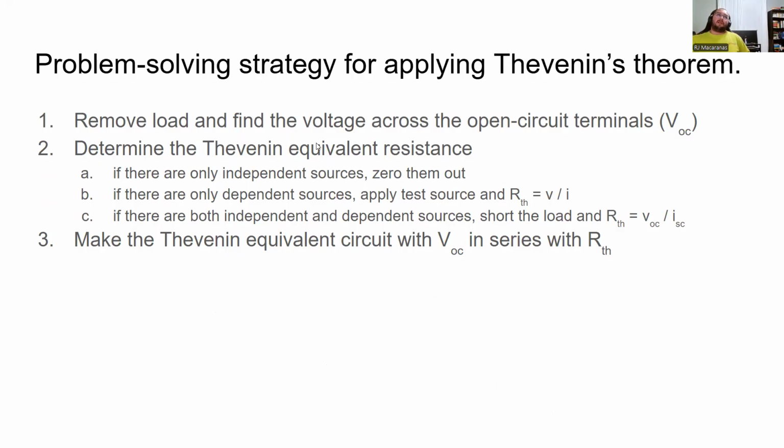You'll need to know what part of your circuit is the load. We remove that part of the circuit and start off by figuring out the voltage across it, due to whatever else is going on.